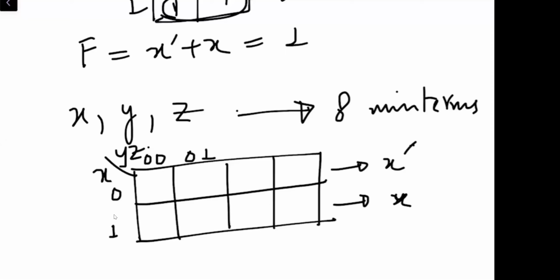We have to have the understanding that only one of the variables can change its value at one time, because otherwise the K-map will not hold good for the Boolean algebra. So we need to have the change in the adjacent column for only one variable, and for that very reason, the next column will be labeled as 1 1 over here.